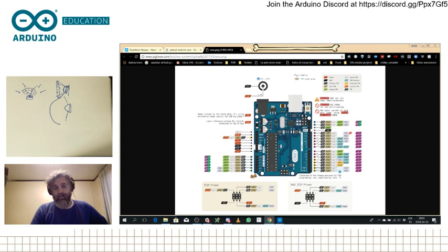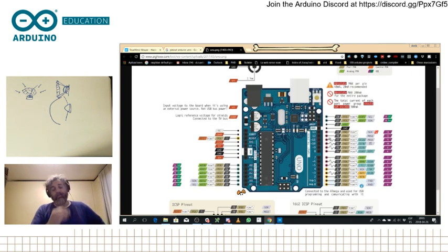And for those of you that are not familiar with this, inside the Arduino Uno, inside the chip, the ATmega328, there are different peripherals. One is doing an SPI connection, which is like a serial port, but can reach faster speeds. And this is the one that is connected to these pins and is used for reprogramming the board. And then there's an I2C that allows you to connect multiple devices hanging from the same line, which is connected on the extra pins that are on top here. I will just mark it with my mouse. These two pins, you see SCL and SDA.